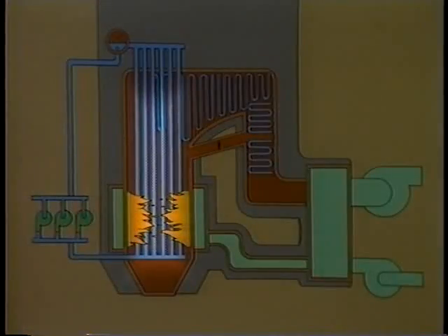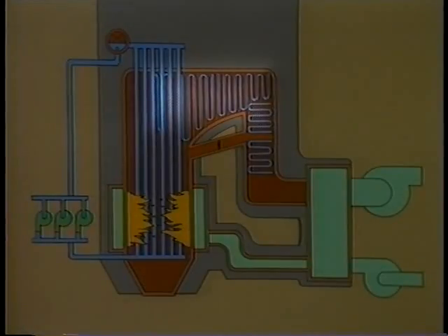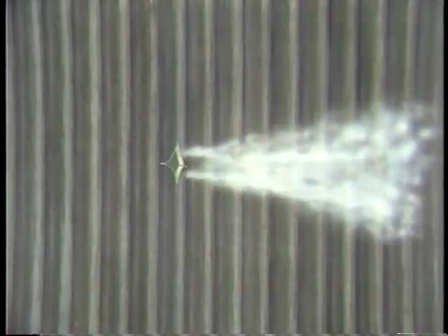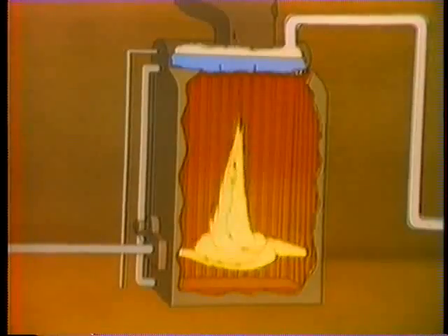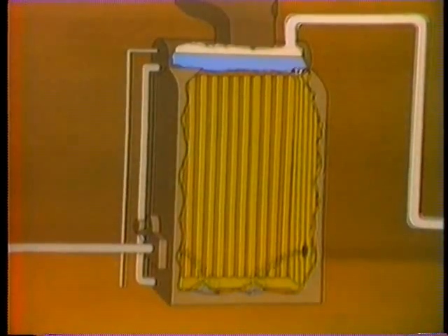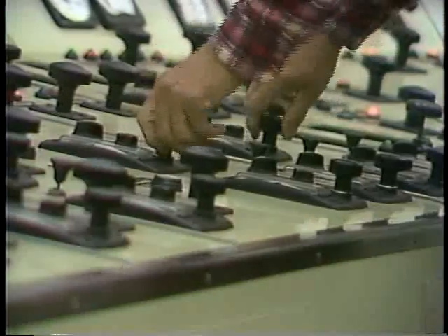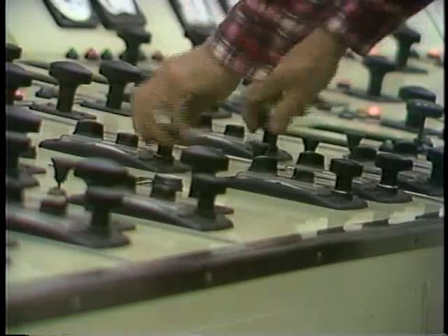Ruptures in the furnace area of the boiler are usually the most critical. Ruptures in the area of the secondary superheater may also cause a flameout, while a rupture in the area of the primary superheater and economizer will not usually upset the boiler flame. When a boiler tube ruptures, water or steam is released into the boiler under high pressure. If the rupture occurs in the furnace area, it may extinguish the boiler flame. Since tube ruptures usually occur without warning, an operator must be constantly ready to shut off all fuel flow to the burners and purge the boiler of combustibles.